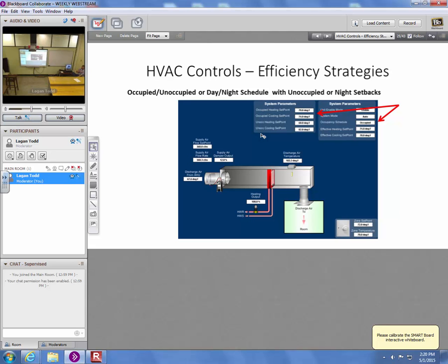Short cycling is a symptom of a problem with binary control, where you say on, off. On, off is okay, but if it short cycles, that can be a problem. It can also be a problem if it's supposed to go on and off, but it never does, and it's always on. That's the opposite of short cycling. That has more to do with undersized versus oversized equipment.